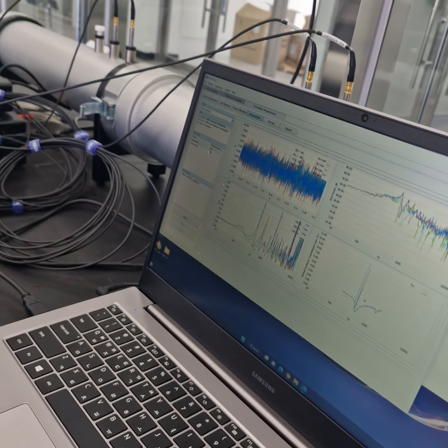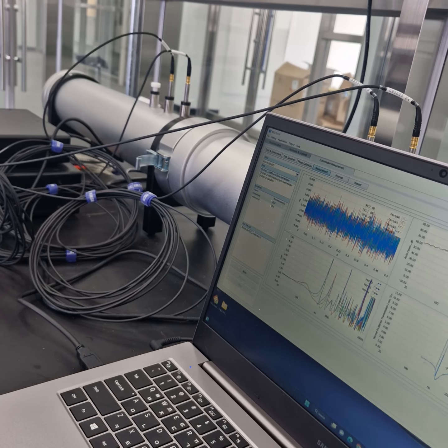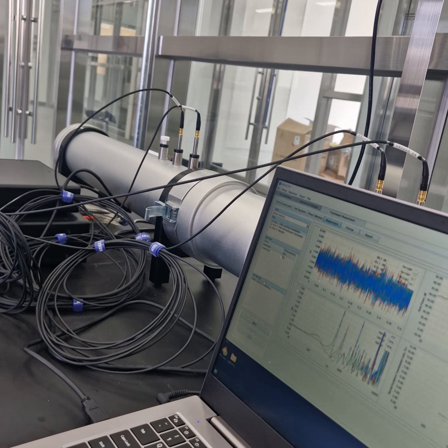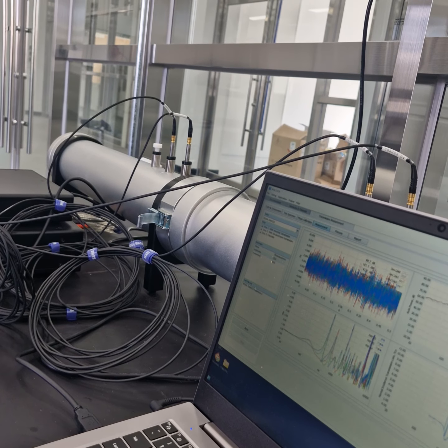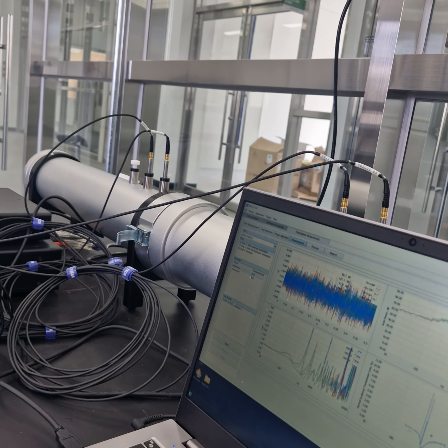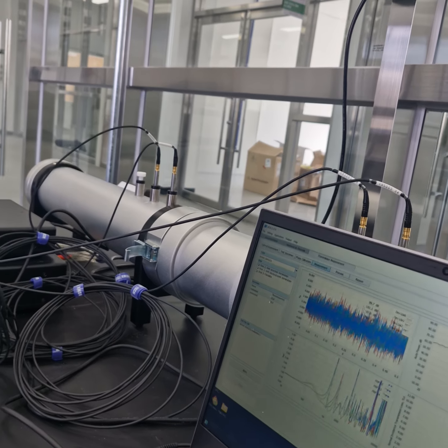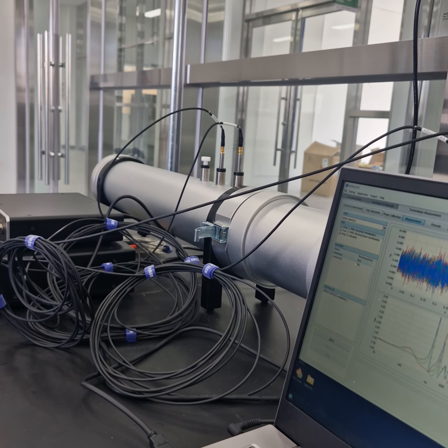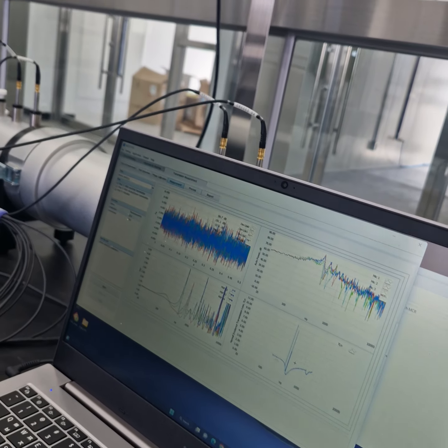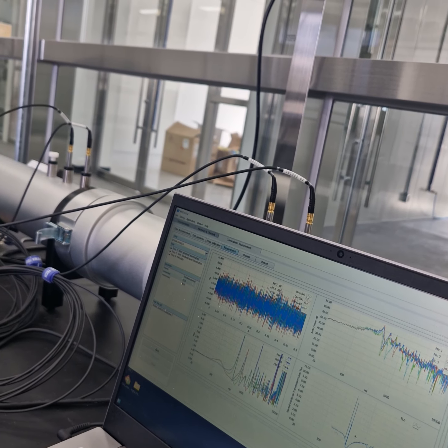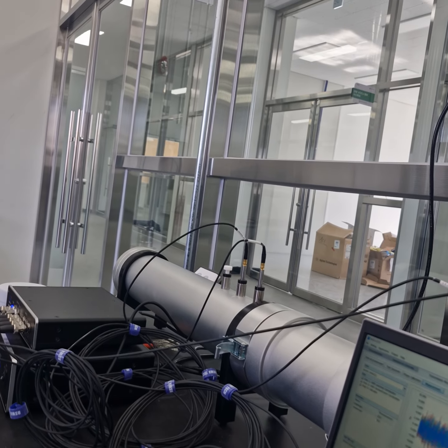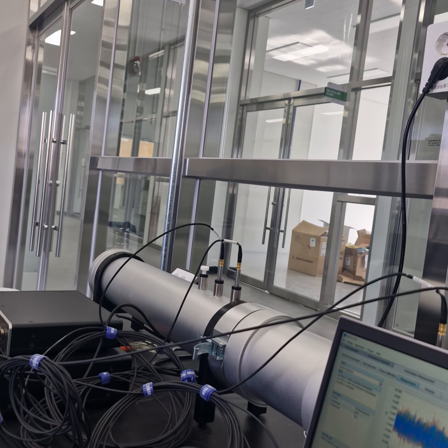Especially for the transmission loss test, the material sample cutting is even more important than for the absorption test. You can imagine, if the sample is too big, it will be compressed. If you compress, then it will have a peak or a dip. If it's too small, the sound will leak through the material from the edges.